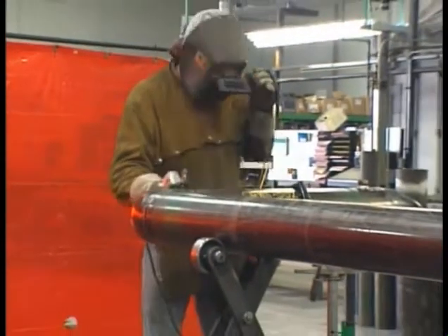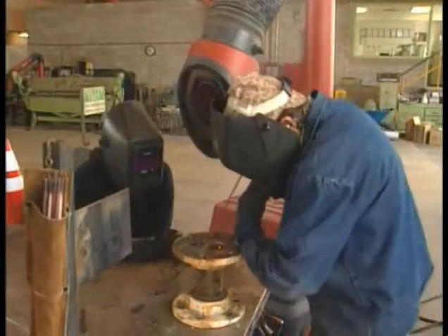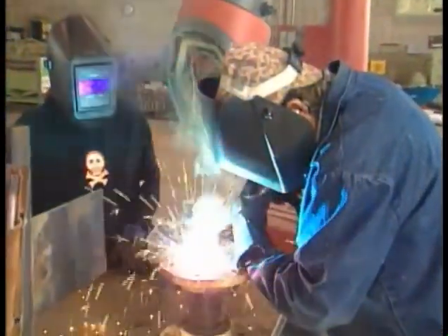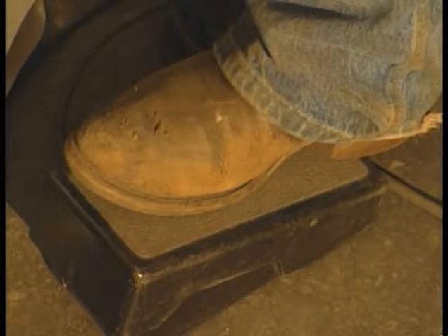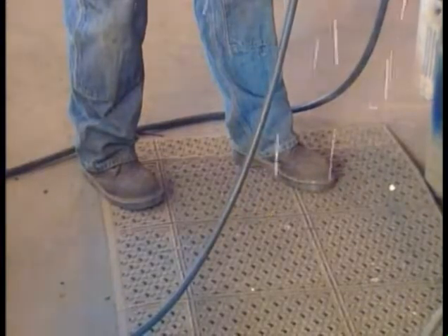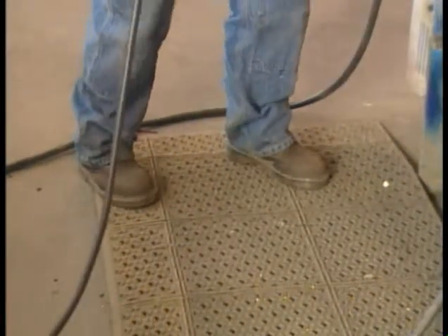If you aren't wearing a special welding outfit, be aware of cuffs and pockets on your shirt or trousers since they can catch and hold hot sparks as you work. The same goes for your shoes. Low-cut shoes allow sparks to end up inside the shoe. Also, be sure your shoes or boots are heavy-duty enough to keep sparks from burning through the shoe top.